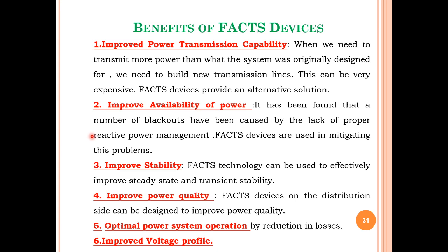Finally, we learned about the benefits of FACTS devices. These are the points we have to remember. Improved power transmission capability. When we need to transmit more power than what the system was originally designed for, we would need to build a new transmission line. But there is no need to build a new transmission line whenever we go for the FACTS device. We can use the existing system. That's the main thing. I can use the power transmission capability efficiently. That's the first point. No need to build the new transmission line. FACTS device can be the alternate solution for this.